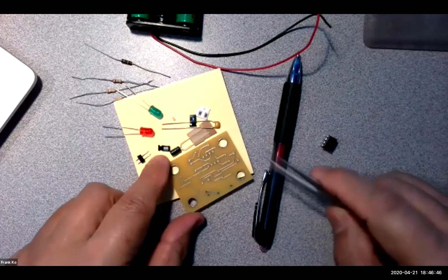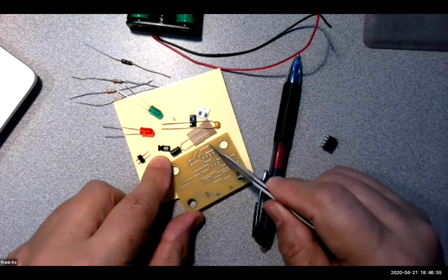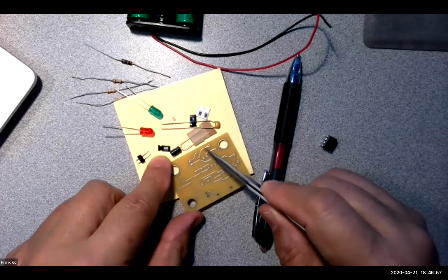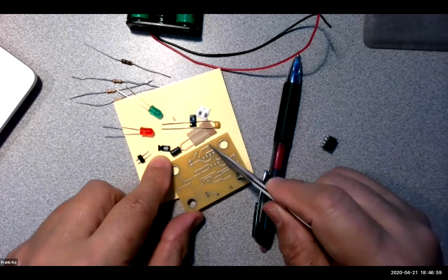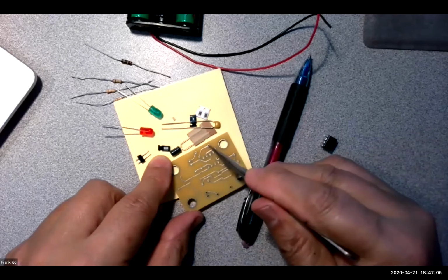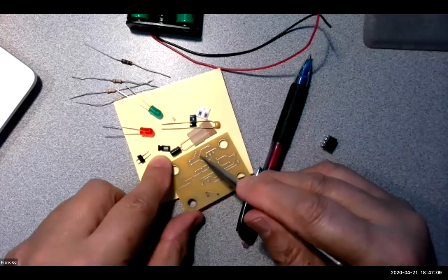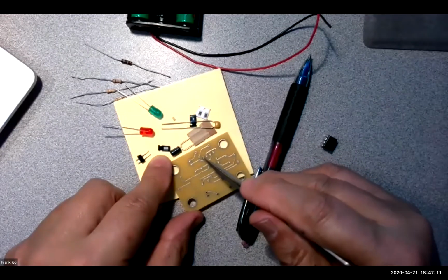And the learning exercise is, if this trace over here for this particular component is burnt, and you don't have anything for that wire to solder to, well, you still have a little wire over here. And so where does this trace connect to? This particular trace connects to this point over here. So you follow the trace from where you've lost it, where it's burnt off the board. You follow the trace that's on the board to the next connection point. Ah, it goes over here.